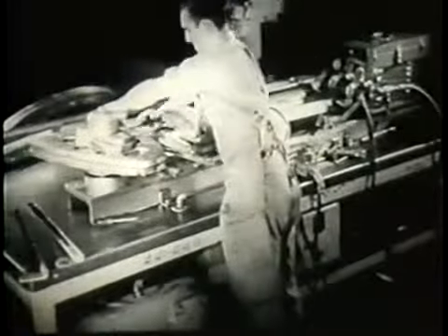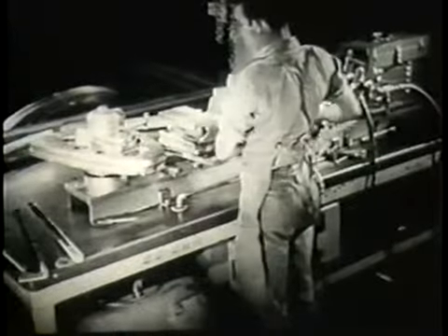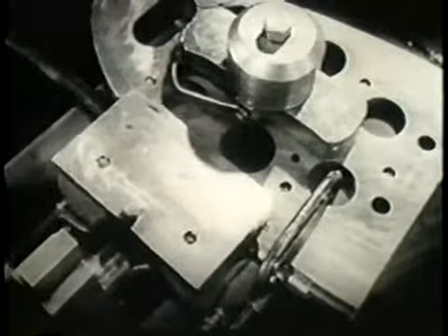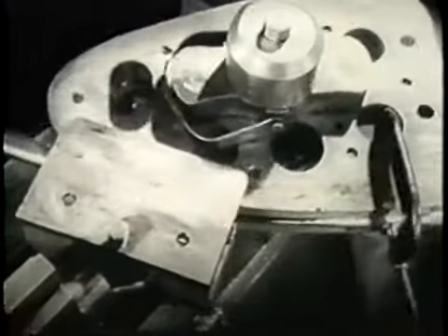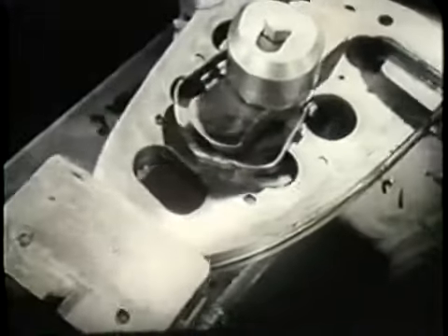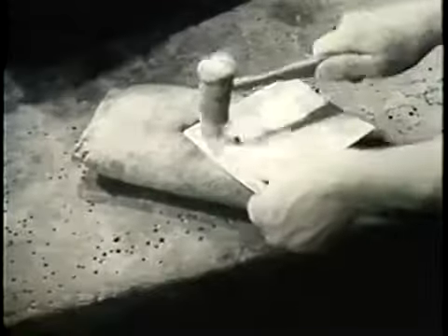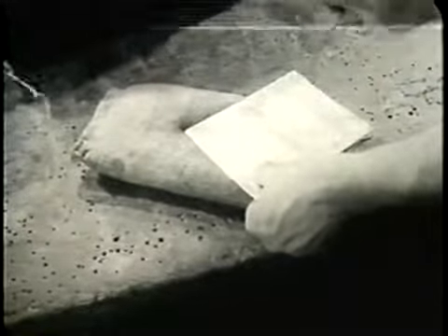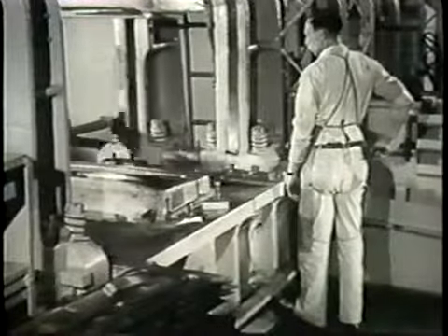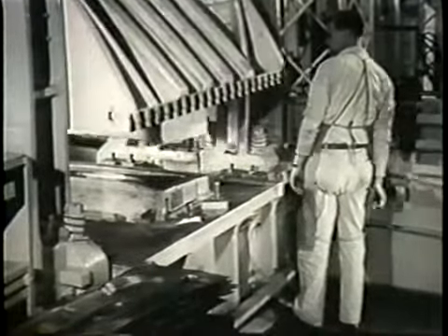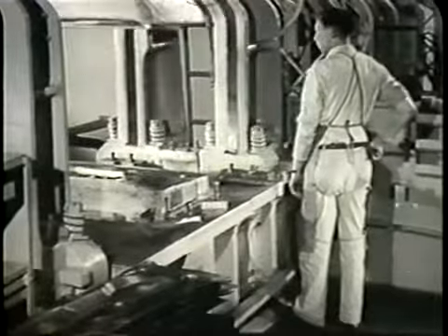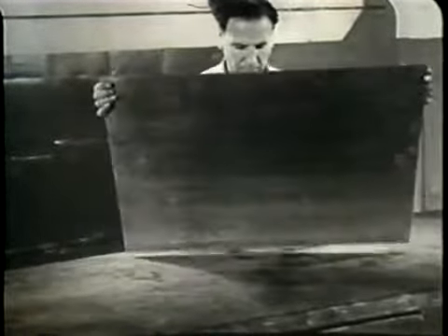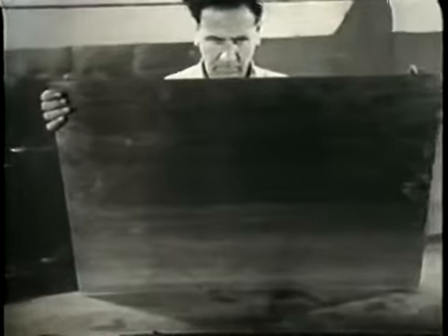Cold working of aluminum alloy is essentially the result of applying sufficient force to the metal to cause permanent deformation. This is true whether the force is applied by hand, by hammer, or through machines of large load capacity, such as the drop hammer. These operations result in strain hardening or strengthening of the metal.